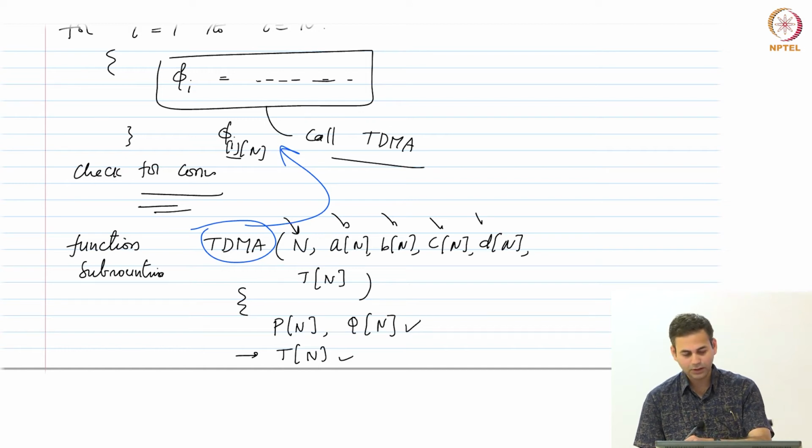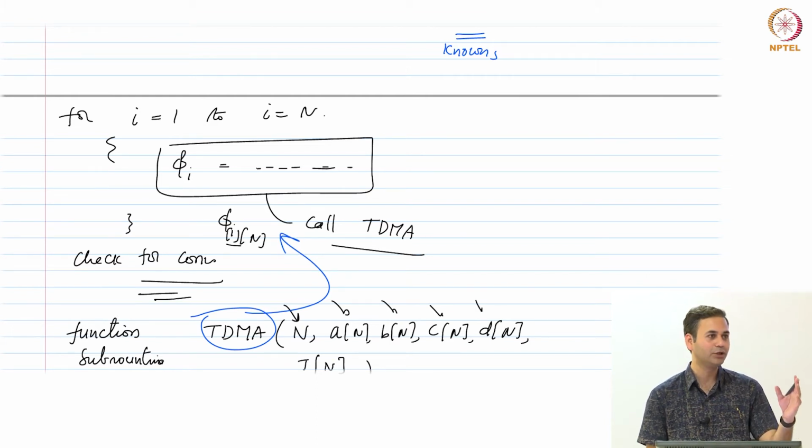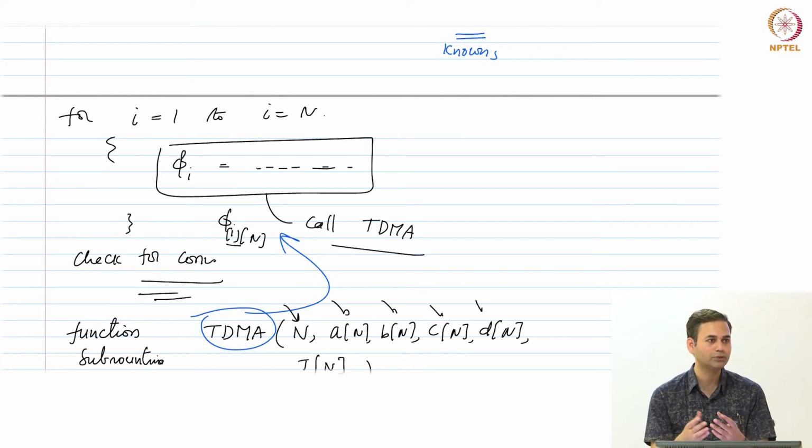I think the question is again, why is it Gauss Seidel? I think you are not happy with the word Gauss Seidel. So the thing is, think of a 1D situation. You have some cells, you calculate the value at the P cell and you move on to the next cell, right. That is what you do in Gauss Seidel. The same thing is what we are doing in the line by line TDMA, except that instead of calculating one value, you are getting values for a row, for the entire y values, in one shot through TDMA. That is why I call it Gauss Seidel, but we can just say line by line TDMA, okay, if you are not happy.